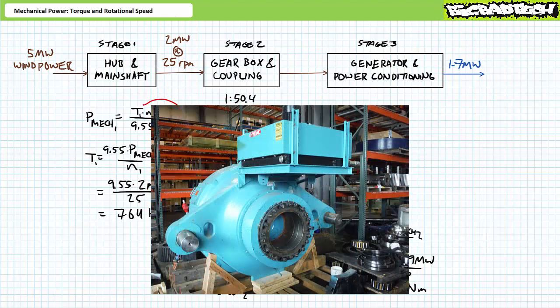It's for this reason you'll sometimes see a radiator or a heat exchanger used to cool the gearbox oil and rid itself of this heat so the oil doesn't thermally degrade and the gearbox continues to function properly. This also explains why gearboxes are built out of heavy metal rather than compressed cheese. The housing must be robust enough to absorb and dissipate the losses inherent in its operation.